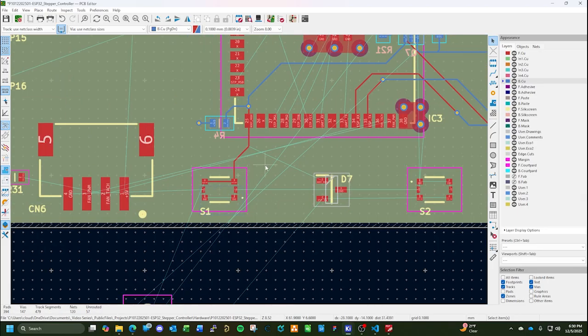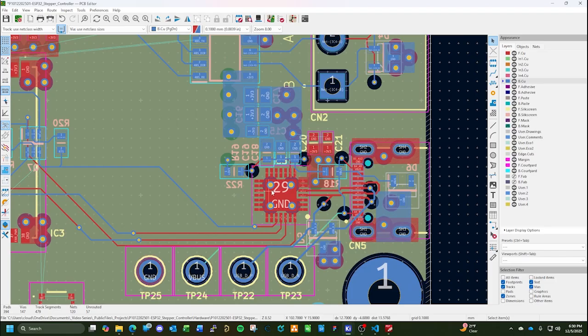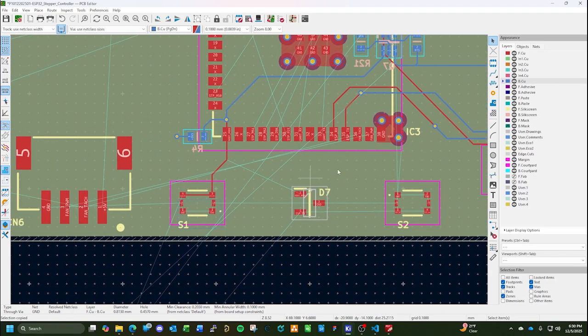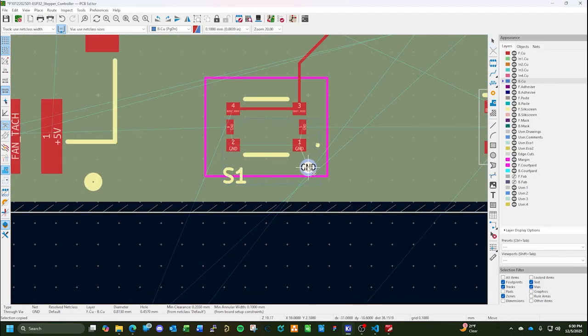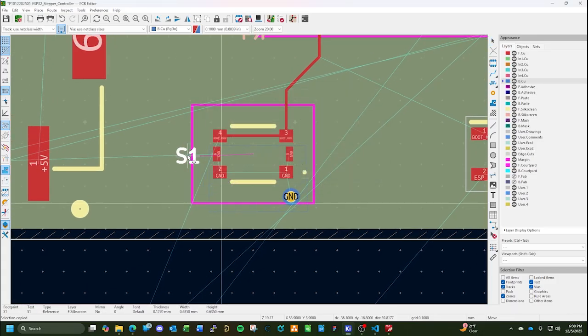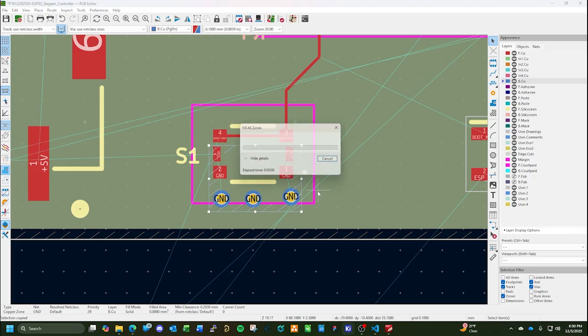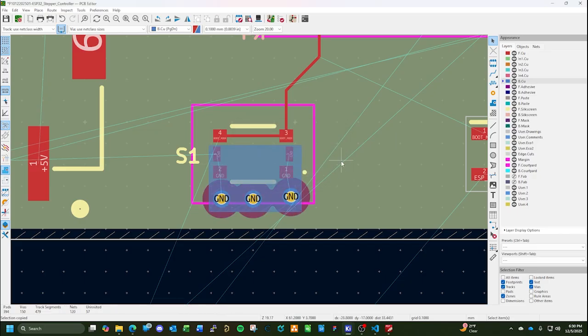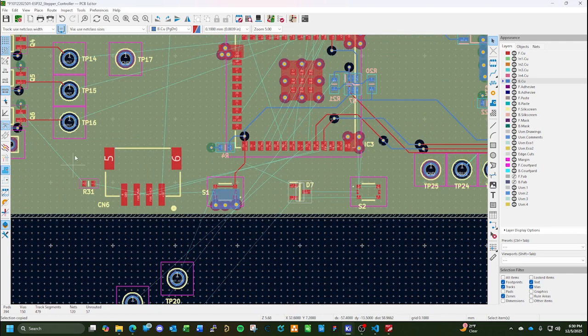All right, so we want to go get some vias. Although we don't need them, but let's just do it. If we're gonna do it, let's just do it right. Let's give this guy some chunky power vias. Again, it's a push button switch. You don't need to, but for the sake of consistency, let's just go ahead and do it. Give this guy these chunky power vias. A little angled off. Fill that in. Great. Now we're going to go and throw text in.